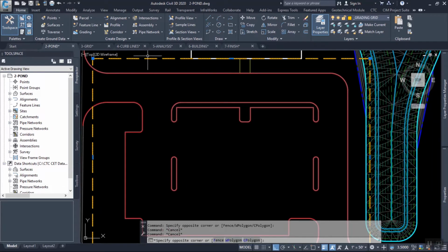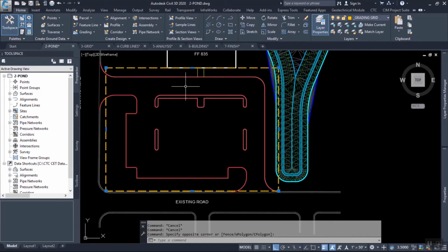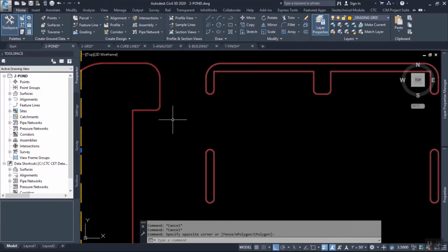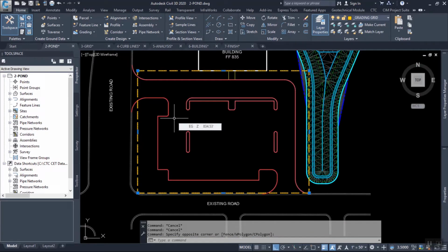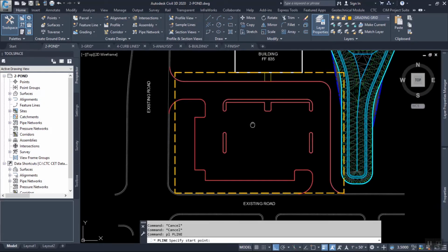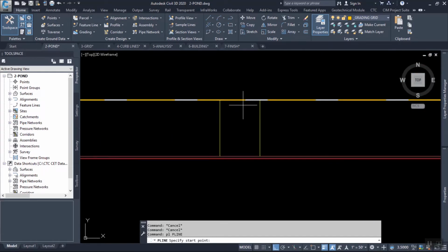Okay? I'm going to turn this thing into a feature line in a bit, but I also need more feature lines that represent swales and ridges in my parking lot. But what I'm doing is ignoring a lot of the key little geometry points, these curb islands, this kind of stuff. I'm considering them for where swales or ridges go. So what it looks like, we start putting it together.